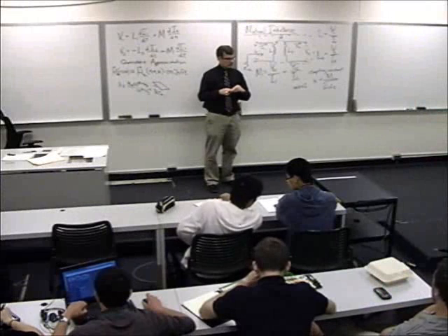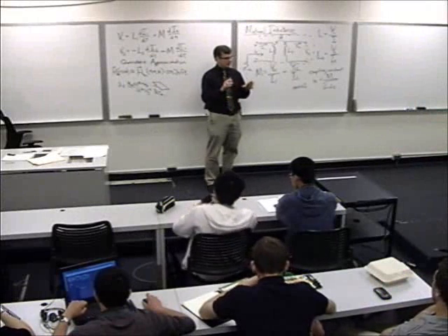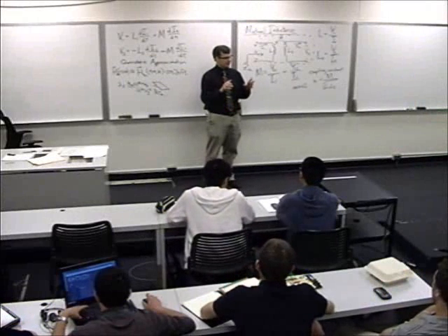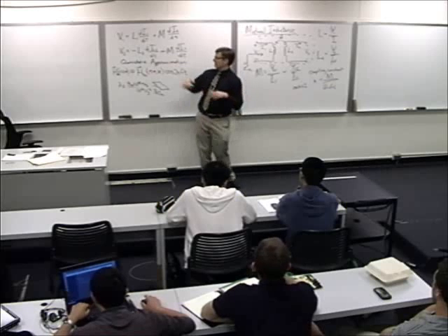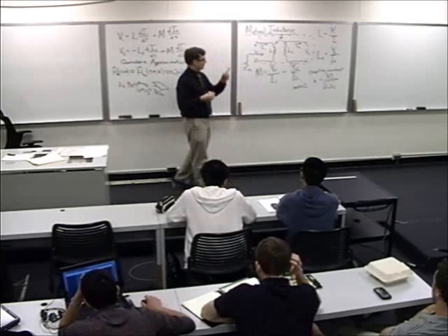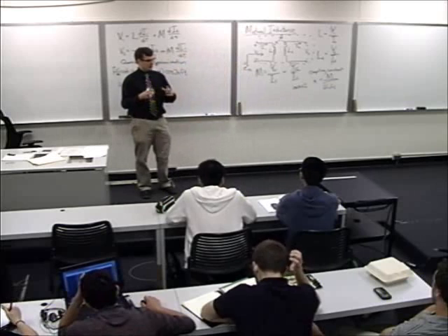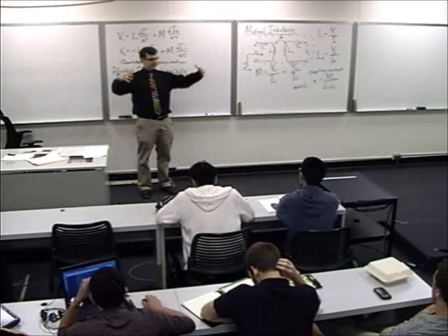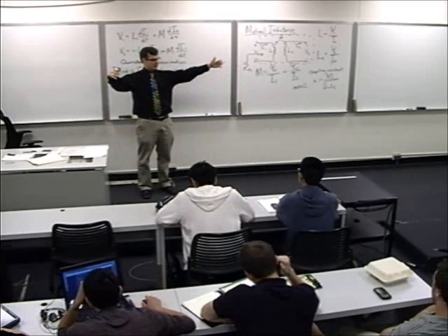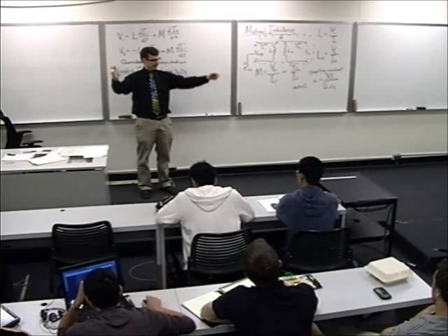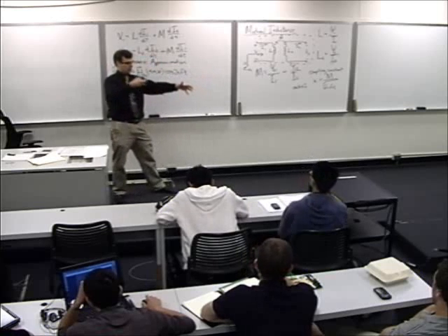Well, what happens is at really high frequencies, the device starts to radiate, and you can just throw that little circuit model that I had over there out the window, because there are now modes of power leaving the device. It's almost like an extra impedance drawing power away, an extra resistance drawing real power out of the system.